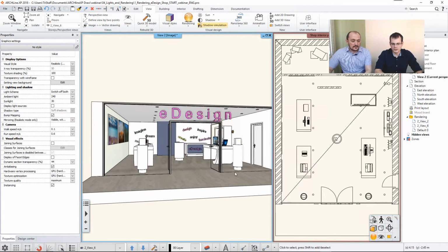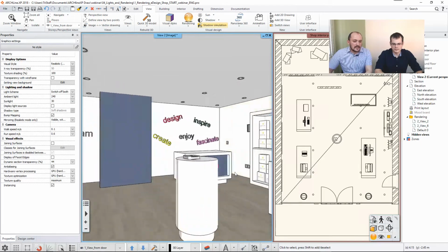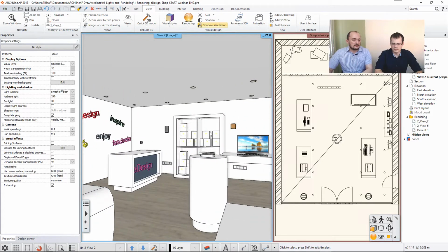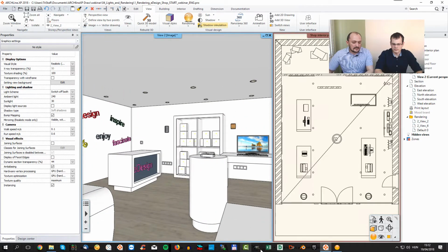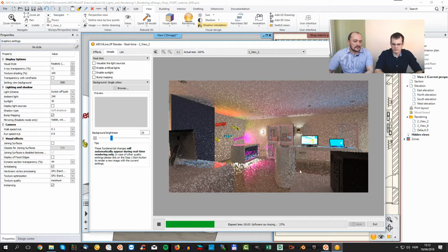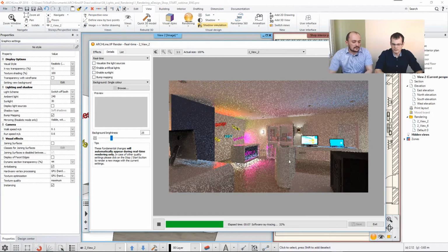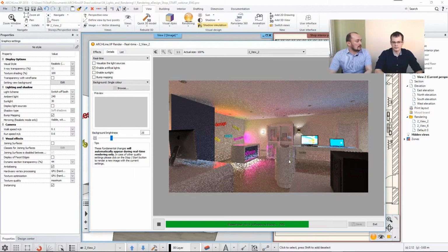So now I'm going back to this view, and let's focus on this same part first. And then talking about filtering. Now, as you can see, we see all sorts of details, also the furniture and things like that. So I think this is when we can also talk about how you can optimize your model for rendering. Now, for example, I'm about to focus on materials, lights and things like that, so I don't need many things here.